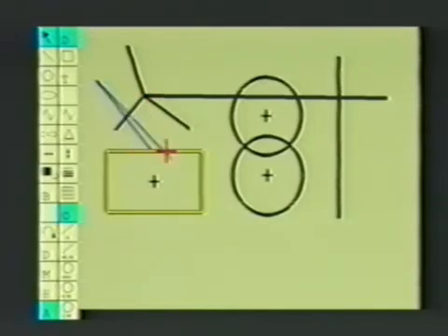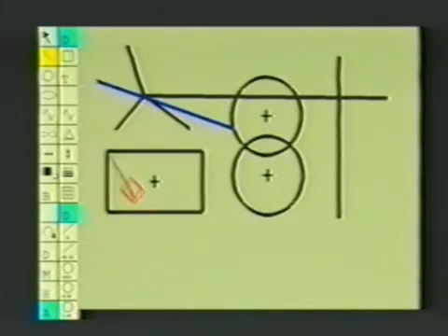To show snapping, feedback lights up the object snapped to with a yellow stripe and changes the cursor's shape depending on whether it is snapped to a point or to an edge. When multiple objects are close to one another, pressing the cycle button selects among them. Snapping is used for all drawing operations, such as selecting, dragging, and creating new objects.